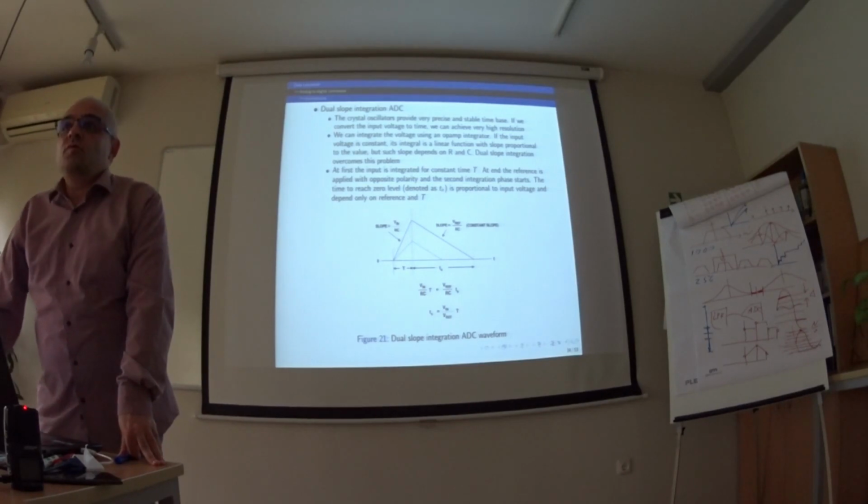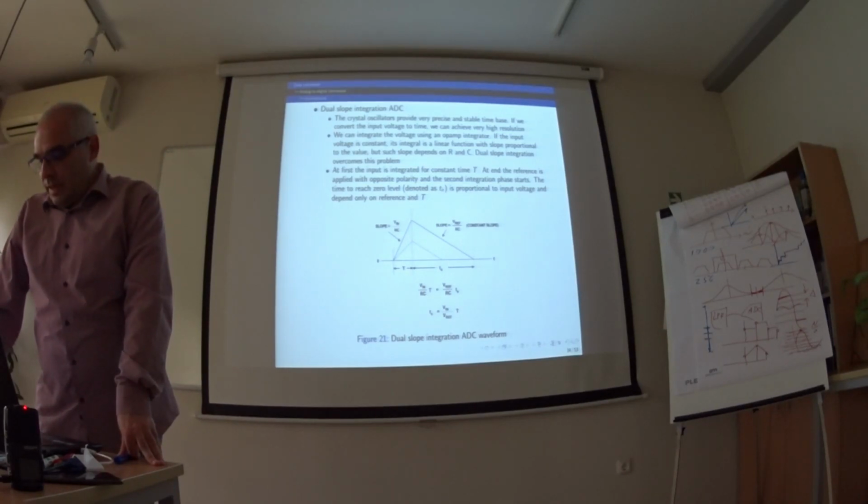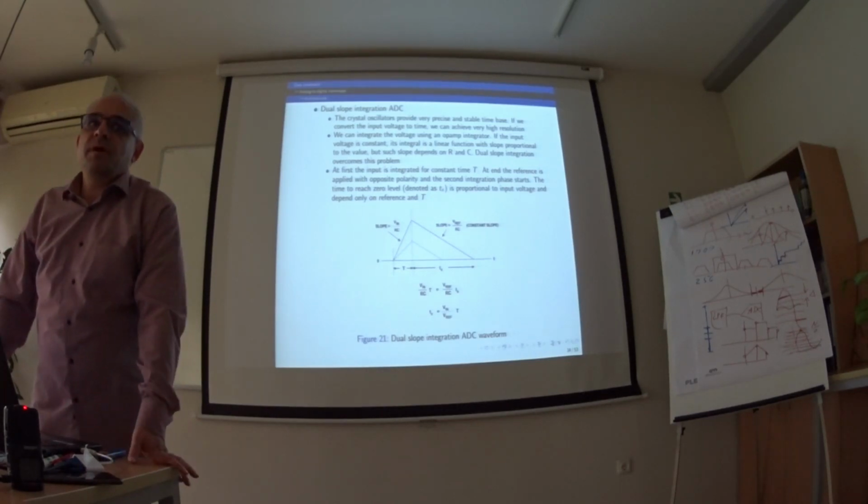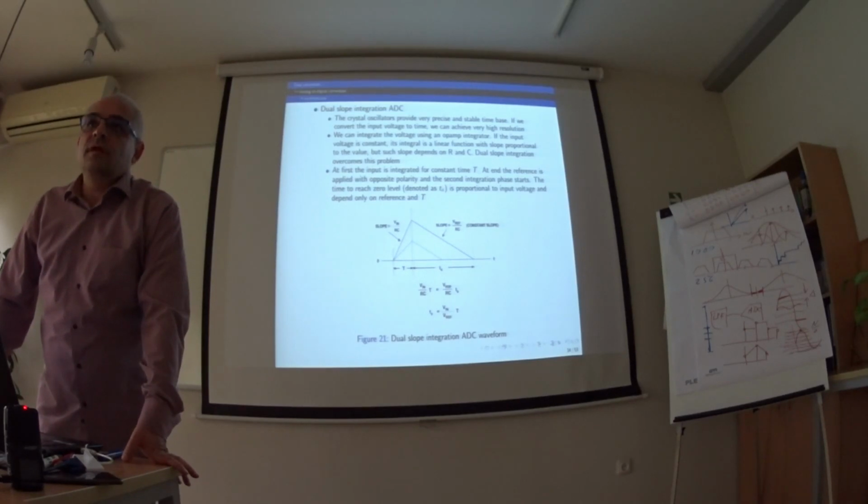Next architecture, dual slope. We have very precise crystal oscillators, very fast, with very stable frequency. Why is it important? Because we can convert the input voltage to time.